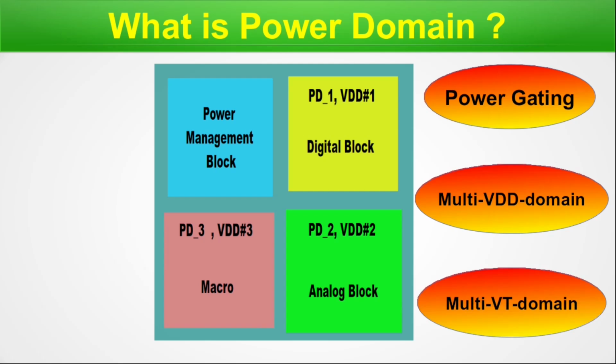And multi-VT domain. Definitely, when we are working on such power domains, it is certainly logical that we are operating with the VDD, and as per the ITRS technology node, when any particular device, any MOSFET, is working on a particular VDD, its threshold is already defined with the ITRS roadmap. You can go to the ITRS website and check these facts by yourself. I'll provide the link in the description. That's why if the VDD is different, it is logical that multiple MOSFETs inside those blocks will have different VT. This is as per the technology roadmap.